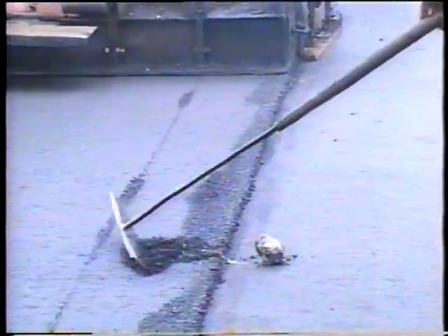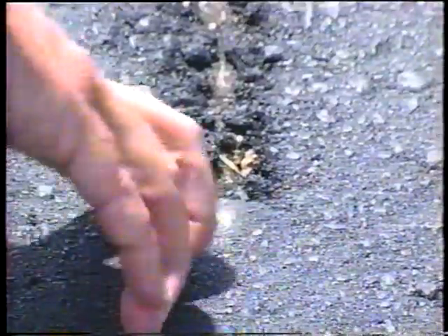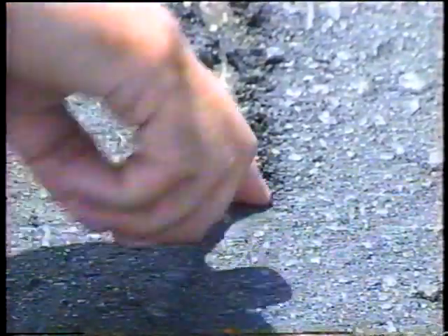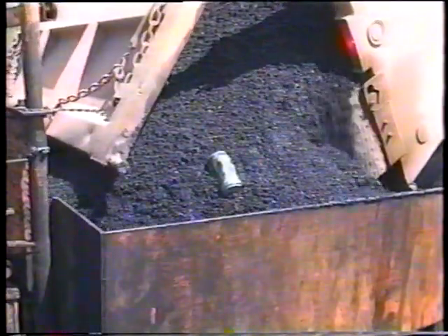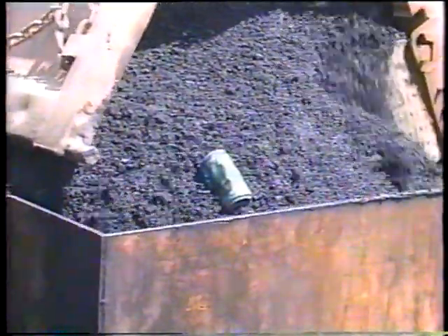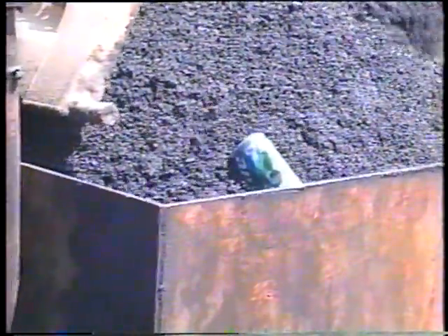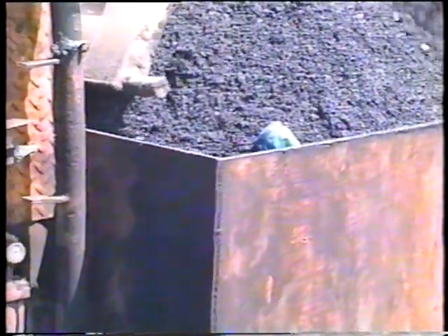Another thing to look for in the mix is debris, or perhaps an oversized piece of aggregate. Here, a large rock got caught under the screed, causing this long gouge in the surface. Improper screed extension mounts, or an unheated screed at the beginning of the day, can cause similar streaking and other mat problems. You never know what might get into the mix, or what might get thrown in the hopper with it. You may be aware that some parts of the country use recycled asphalt material. As of yet, though, no one recommends paving with recycled aluminum.